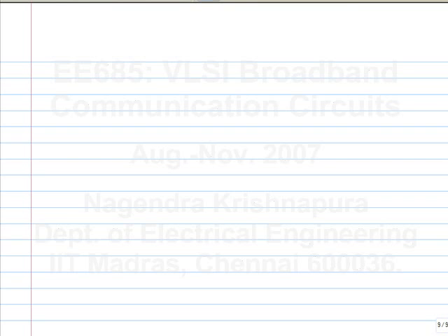So let's go back to the original motivation for coming to the type 2 PLL. In the type 1 PLL, we saw that reference feedthrough was a big problem. When we reduced the reference feedthrough to some manageable level, like 1% of the main carrier level, and that itself is not very good, the range was very small. What is the reference feedthrough in a type 2 PLL? Here I am talking specifically about the 3-state phase detector.